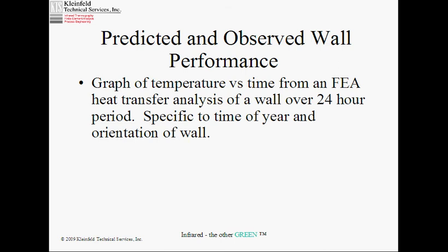I described this already to you. We're detecting delamination or voids or bad material because of the difference in their heat transfer characteristics. So far we're, quote, looking at temperature, taking pictures really of radiation, but the approximation is we're looking at temperature.